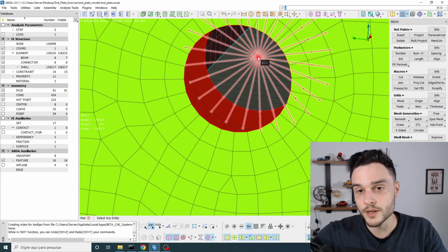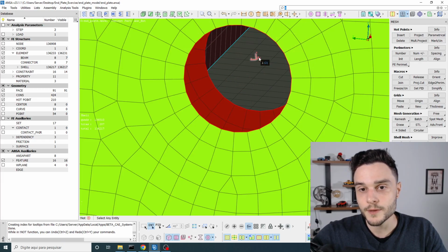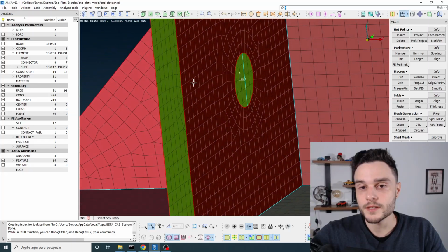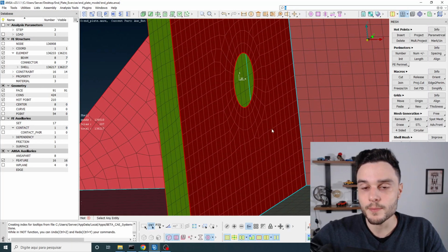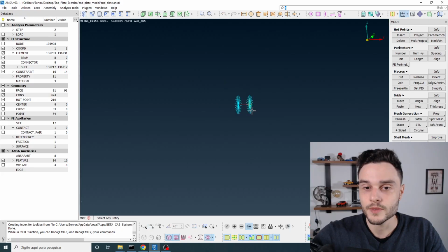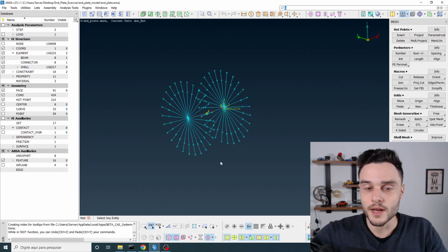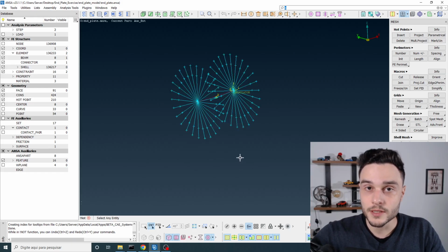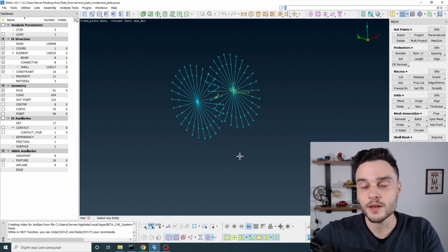And the translator is also connected to the coupling that we have there. And the coupling is connected to the column flange. So here you have isolated all these items. And this is the bolt modeling strategy that we are using for this first run. And then in the next run, we are going to consider solid elements for the bolts, washer, nut, and etc.